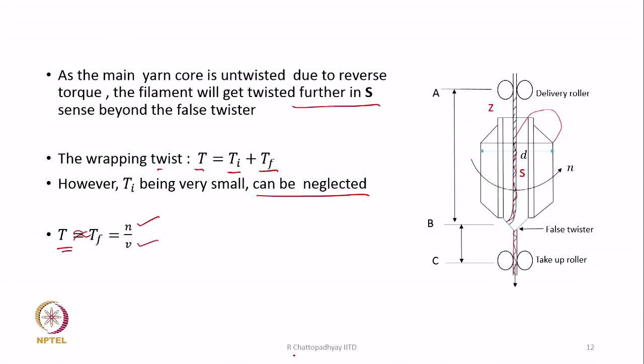But this speed difference between the spindle and the traveller in the case of ring spinning is so low that we practically neglect it, and we calculate the twist on the basis of the ratio of spindle speed by delivery, because the error that we make is too little and has no practical significance.